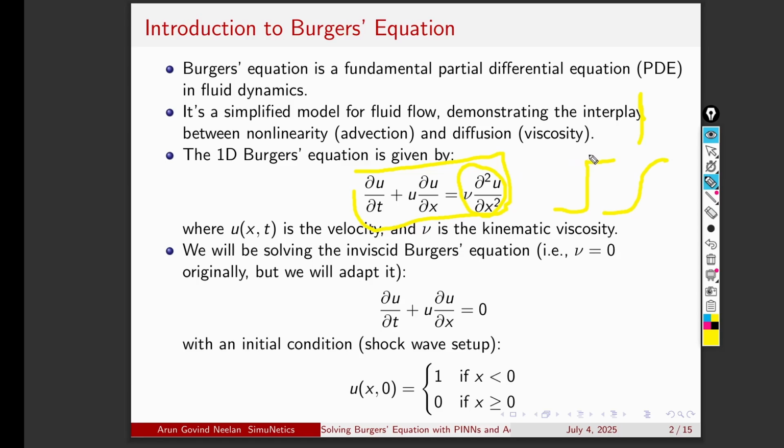That's why, in any numerical methods or PINNs, we try to smooth the shock if possible. If we don't smooth it, it's almost impossible to solve using most of the existing methods, especially shock-capturing methods, numerical methods, or even PINNs. We know universal function approximation is only valid for differentiable functions, but the Euler equation, which has a shock, is non-differentiable. So that will become impossible. That's why we will use adaptive viscosity.